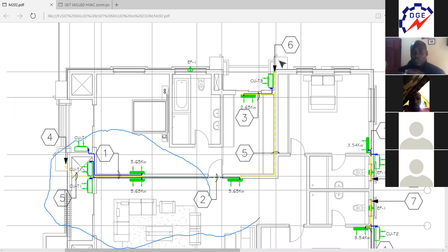So if you are doing a design or an installation, you have provisions for every condensate coming out of every AC that can be taken into the ground, or into condensate manholes, or into common drainage pipes that can actually get the water out of the system. Not that you're just dumping the water on the floor within the compound. That is not the neat thing to do.